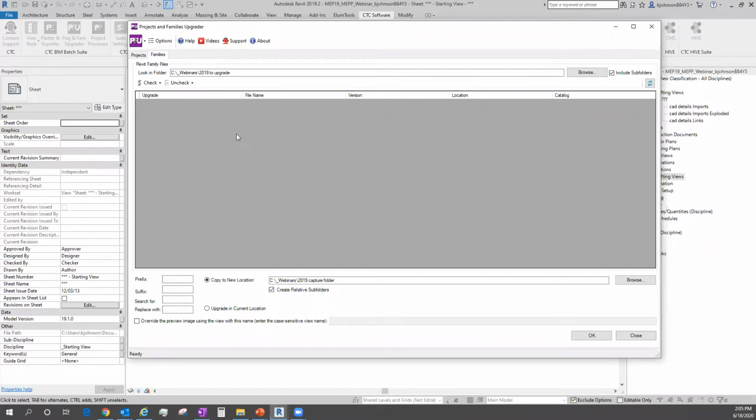A lot of times we would write scripts and try to control that in just Windows, where we would open Revit, open the file, save the file in the current new version, and then save it back to the folder location. But that sometimes got a little tricky because it would save it back to the same folder location. So usually we'd have to grab the entire library, put it into, say, the 2020 new library location.